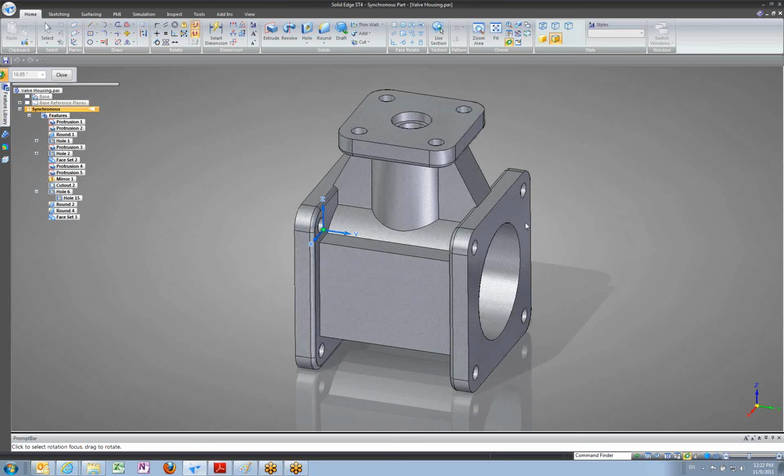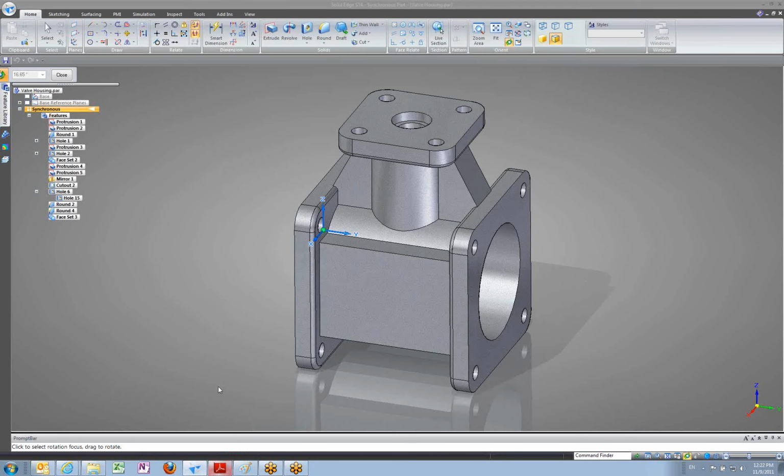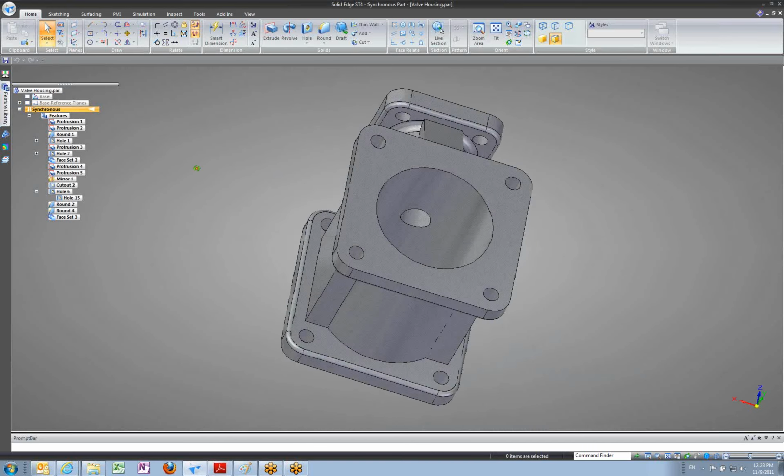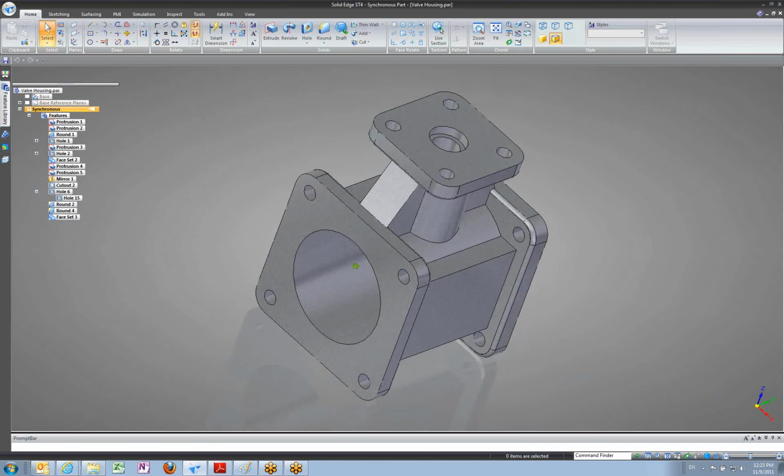The other thing we have is keyboard and right mouse click combinations. I sent this in the original document, the installation, or sorry, that was the document that went out this morning. We sent one out that has a cheat sheet of the keyboard commands, and these are the ones that when you get more experience you're going to use the most often. So the first one is that if you hold down Shift and hold down right click, moving your mouse in any direction will create that rotate.